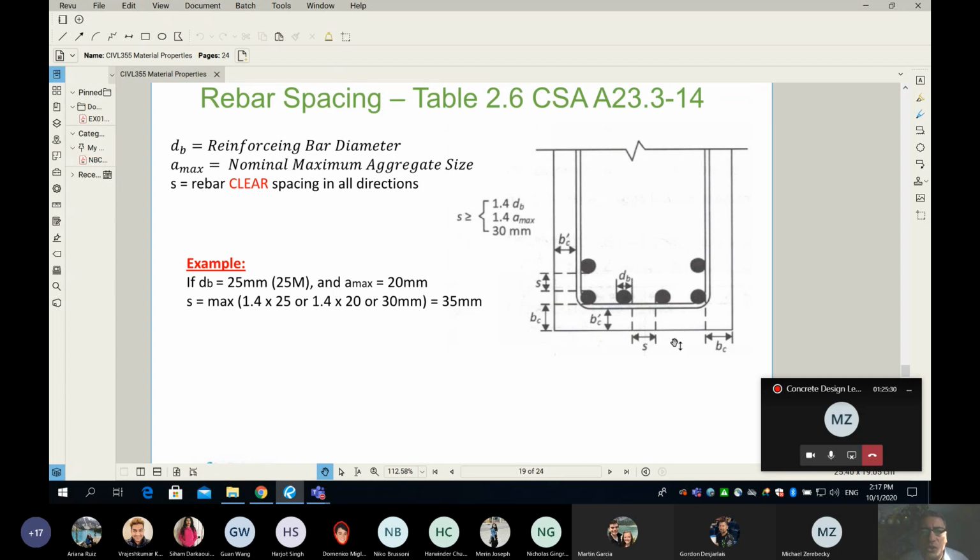Okay, guys, also, I'm not sure if you already have that much experience to have seen bundles. Sometimes we do a rebar bundle. When I say rebar bundle, it means we don't maintain the S, we just bundle them so they are touching each other. So it's not very common. We use it only when there is really so much reinforcement, like a forest of reinforcement in your beam, and this is not the norm for a condo building, or even a high-rise building beams.